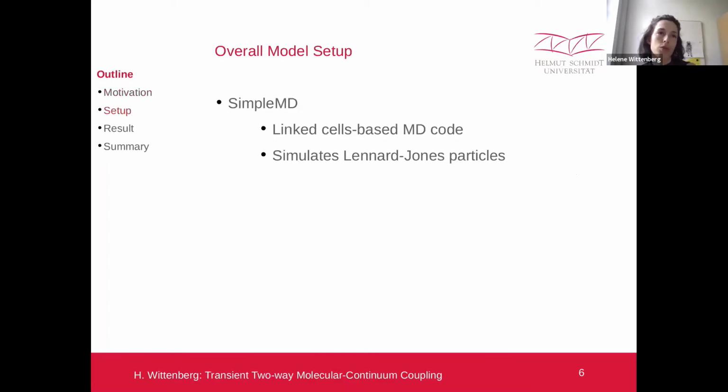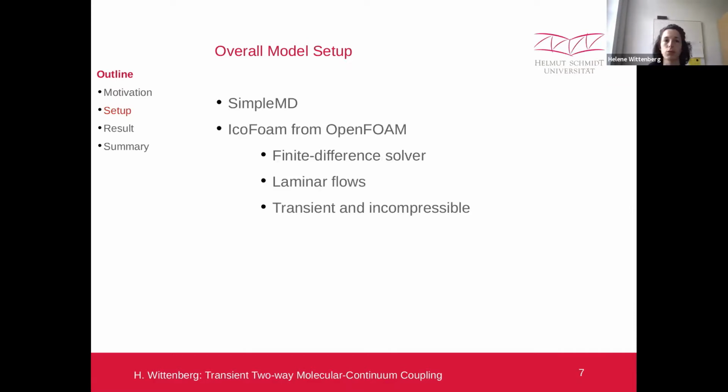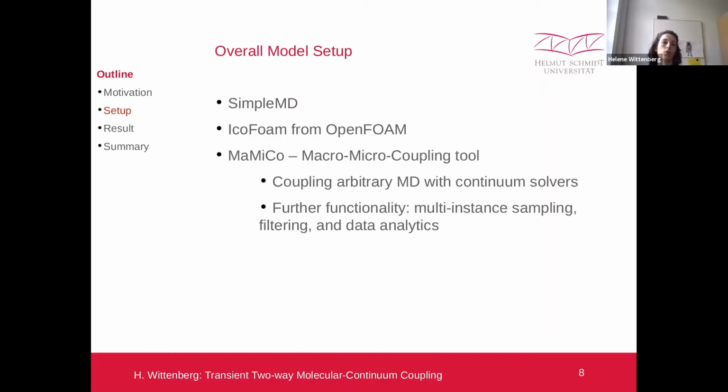But first, I want to present my setup, which consists of three parts. First, we have SimpleMD, which is the molecular dynamic model. It's a linked cell-based molecular dynamic code. It simulates Lennard-Jones particles. Then I use icoFoam, which is part of the OpenFOAM library. It's a finite volume solver. It works for laminar flows. It's transient and incompressible. For the coupling, I use MaMiCo, the macro-micro coupling tool.